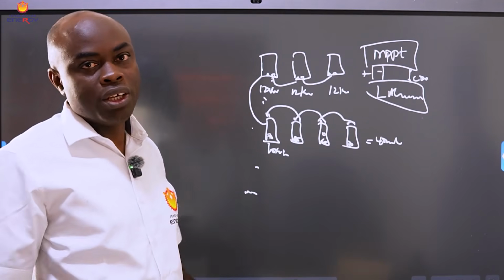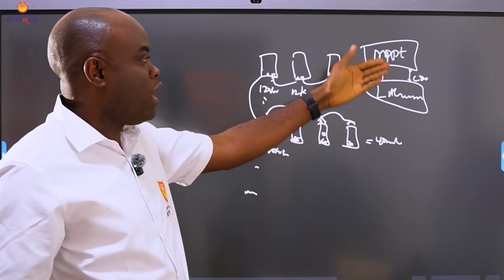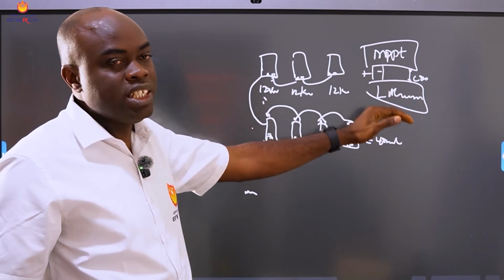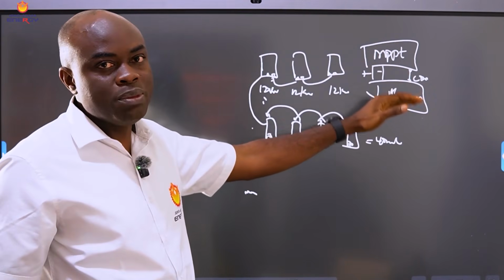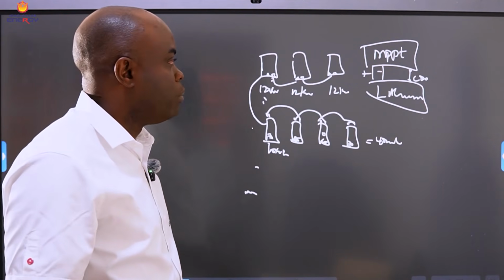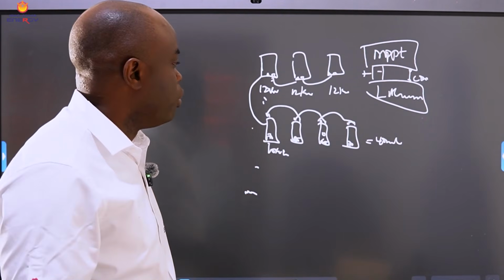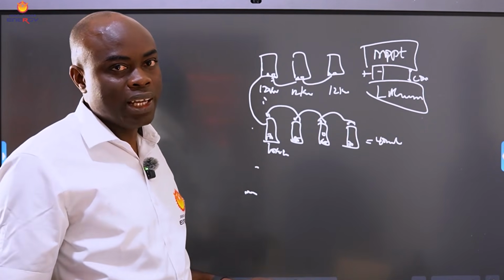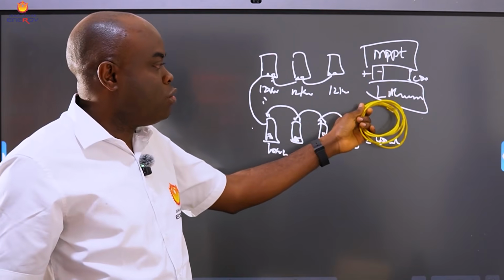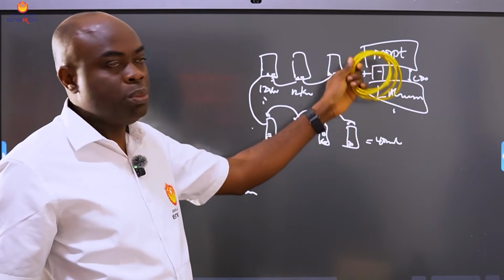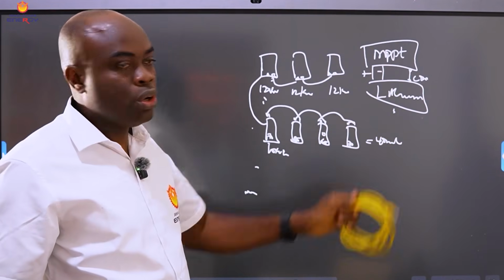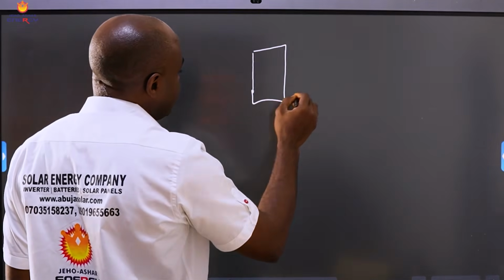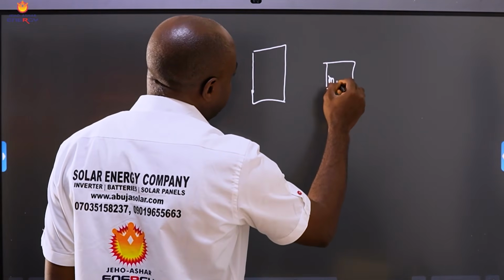You have peace of mind. Your customer will refer you more because you have installed a system that has proper communication, and the charging is being regulated, overcharging is being regulated, the temperature is being monitored, every other piece of information is being picked from it. The depth of discharge is also being monitored. So please, in this era we are in, with a lot of charge controllers in the market and people going to lithium batteries, do it properly: get a communication cable between the MPPT you are using on your site and your battery. And with most inverters, you could connect your MPPT through the inverter.